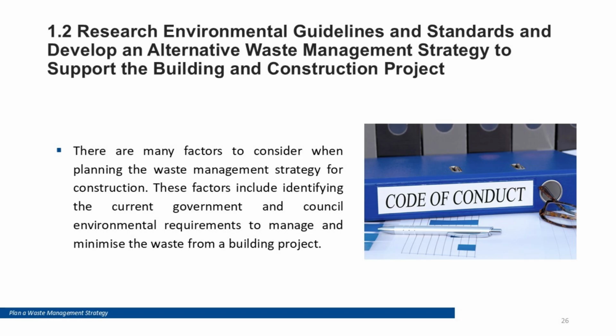After identifying requirements, research environmental guidelines and standards that support better waste performance. This includes industry guidance on recycling, reuse and site controls, plus workplace and client expectations. A simple way to manage this information is a compliance or legal register that lists the requirement, where it applies, and what the project will do to meet it. This keeps responsibilities clear and makes review and updates easier as the project progresses.